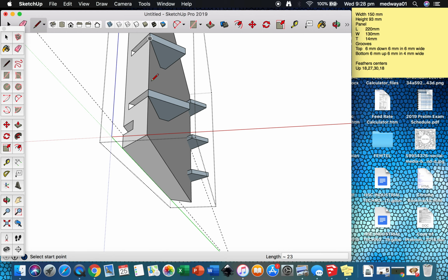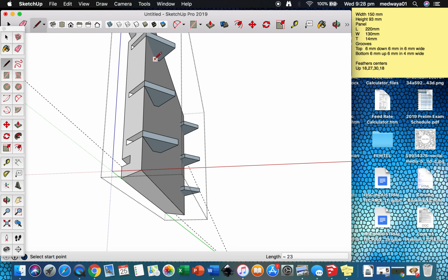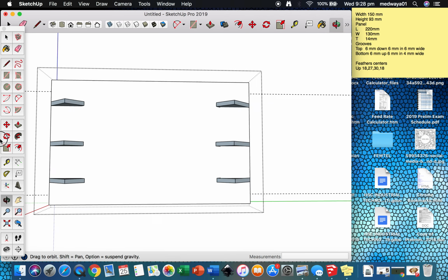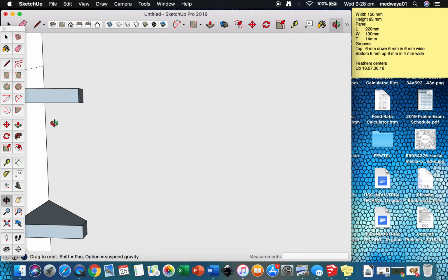This makes that section that we're going to erase later on a separate part and not attached to the drawing anymore. And I'll rotate around to the back. Again, using the orbit tool, O for orbit. Line from there down to there. And I now can erase that.